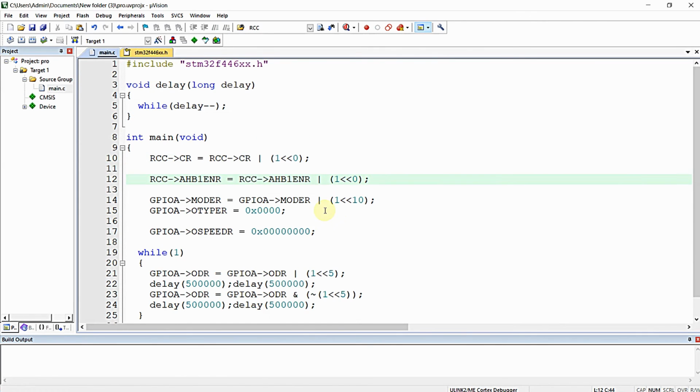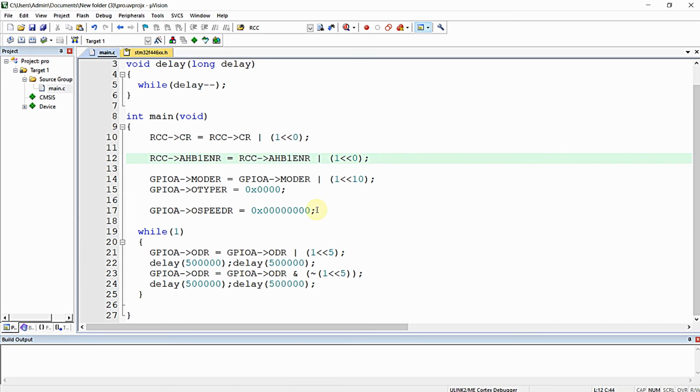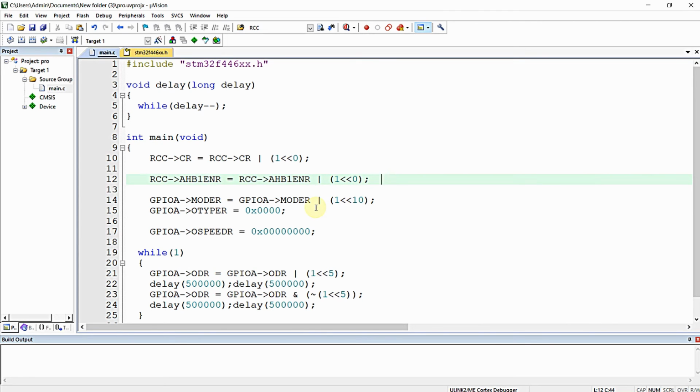And that's it. That's all about the program that you need to write for blinking the LED. We have already discussed this particular program many times in the previous video using our user defined CMSIS structure. So let me just compile this program. Just press F7 on your keyboard, or click this icon at the top of the menu just below the save button, for compiling this program.